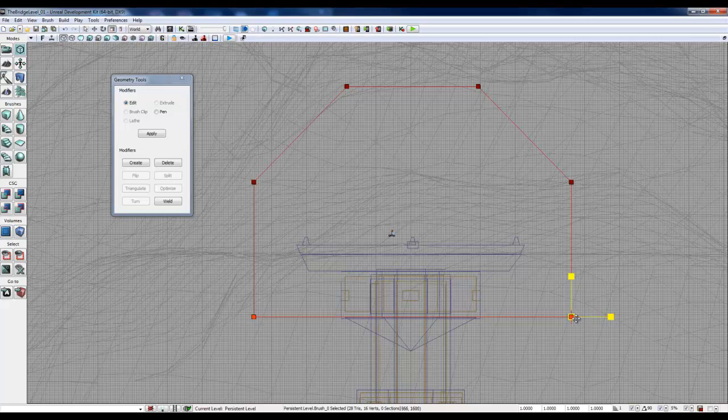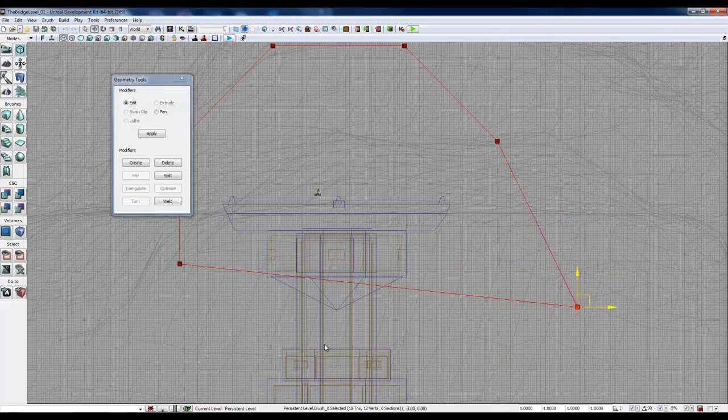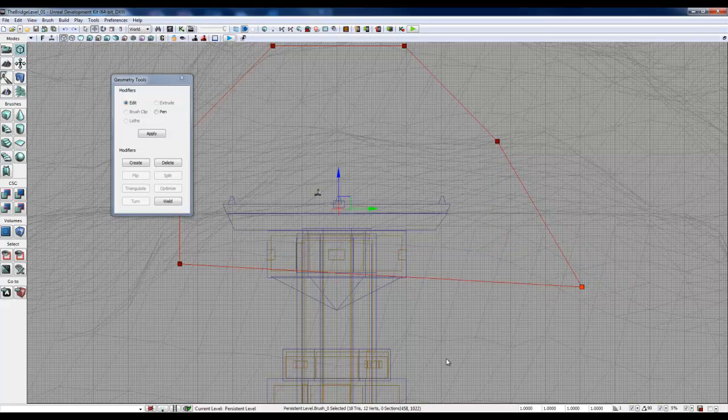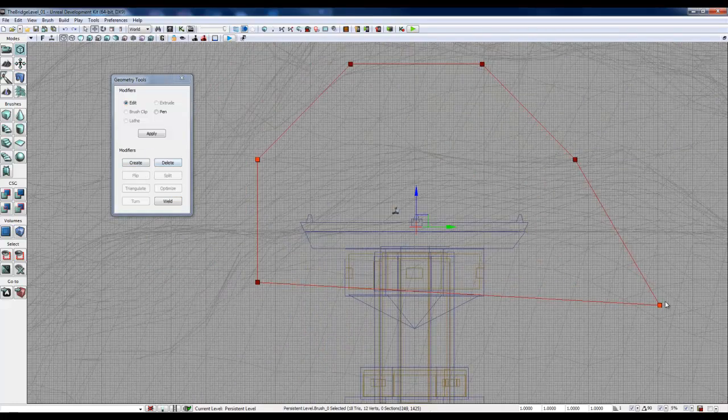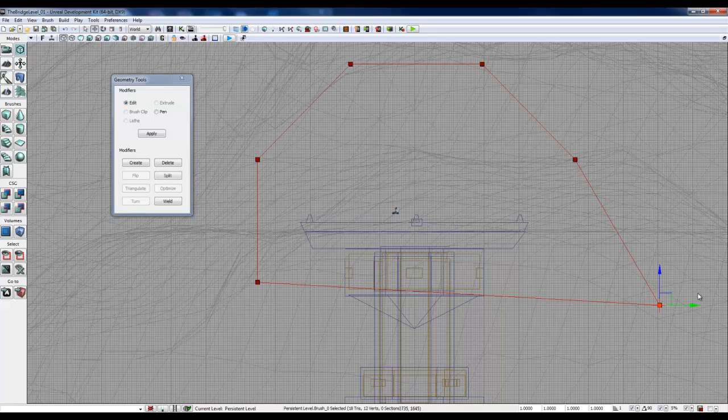And sometimes your transform gizmo thing here is going to look a little wonky. It could look wonky if you're in world, or excuse me, local mode. You want to switch that to world mode. Yeah, I just want to drag. Looks like I missed something, didn't I? Grab that, grab that. Oh wow, I'm really distorting that bad, aren't I? Let's try to get that back into place.